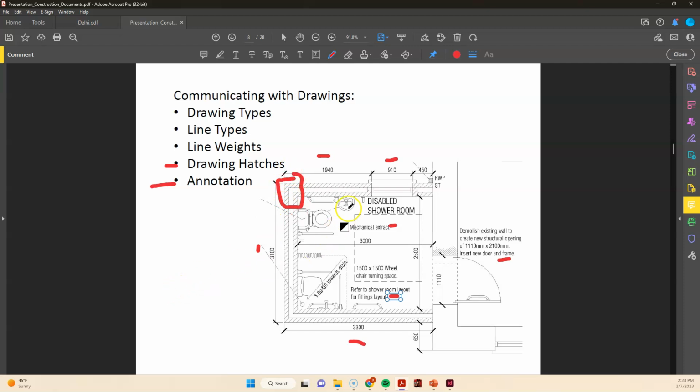And of course here we see plan hatches telling us what that is, which I would expect to be a masonry wall, but a lot of good, thorough drawing sets come with a legend on the cover page. They'll list all of the symbols and all of the different hatches, so that nothing is mistaken. Because in our business, a misunderstood hatch or misunderstood annotation could result in a lot of money and a lot of headaches, to say the least. Okay, so that's the top 5. Those are our biggest tools.